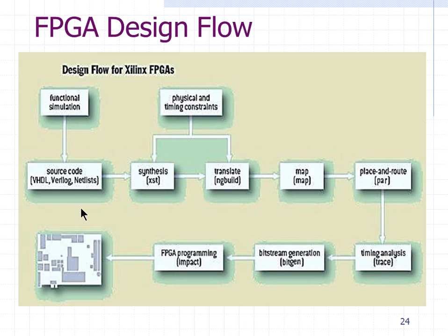Because out of the entire design cycle, let's say it takes one year to design a chip completely, 60 to 65% of the time goes into design and verification, which is the front-end aspect of design. The design and verification will take 60 to 65% or even 70% of the entire design cycle. The back-end part, synthesis, mapping, placement, routing, will take the remaining 30%.